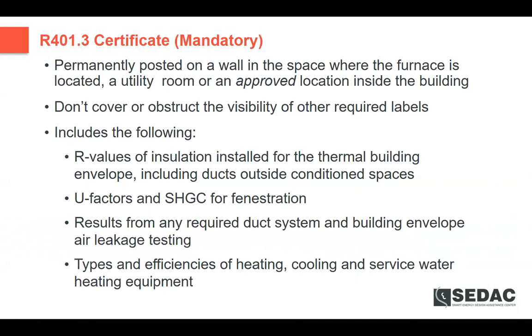But noting, it lists several qualities that must be included on these labels, and some of the reasons that we find this to be very important, particularly when you get into U factors for the fenestration, is yes, the windows come with the label on them, but during construction, that label gets removed shortly thereafter. And so if I end up with a broken window, I need to make sure that I know how good the window was, so I don't end up degrading my energy performance.